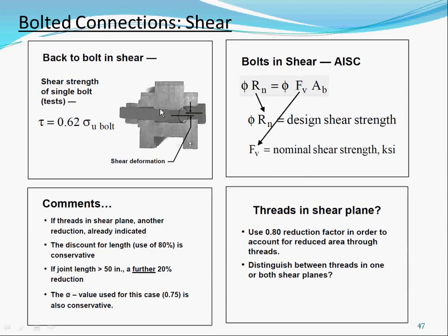So if this one's outside, then you don't have to reduce for the threads, and that's what the X and N are in this bolt table. So let's go to the bolt section and show you guys what it is. When you look at the shear capacity they publish, they have a thread condition N and then X. So when you exclude the threads, you get higher capacity, whereas if not, you get lower capacity, and that's X threaded. And typically they say that's an 80% difference.